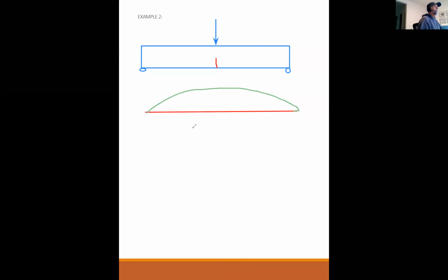So the simple answer to your question, the beam is going to crack on the bottom because it is in positive bending. And positive bending does not care where you put the steel. I could have steel here and I could have steel here, doesn't matter. Positive bending, a smiling face. Yes, it is, but that's the deflected shape. Okay, let me finish this. This is positive bending.